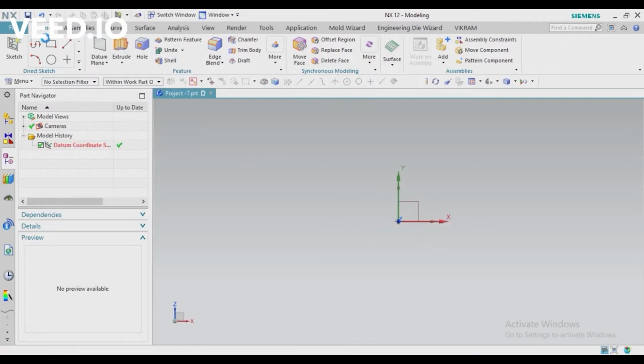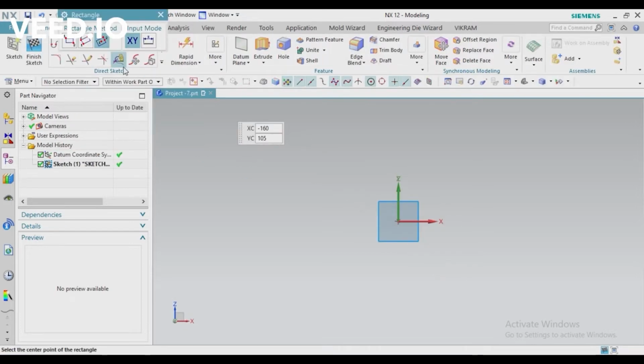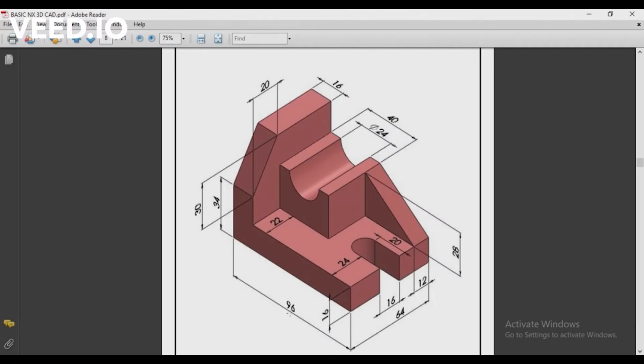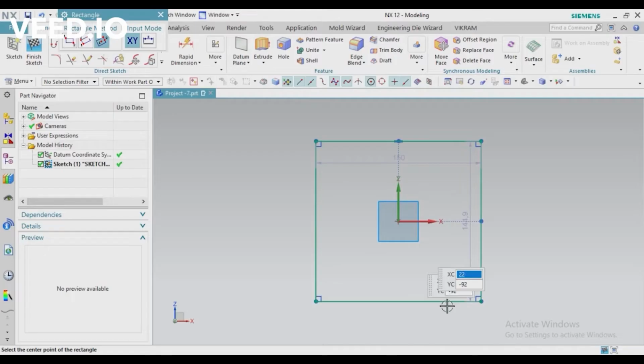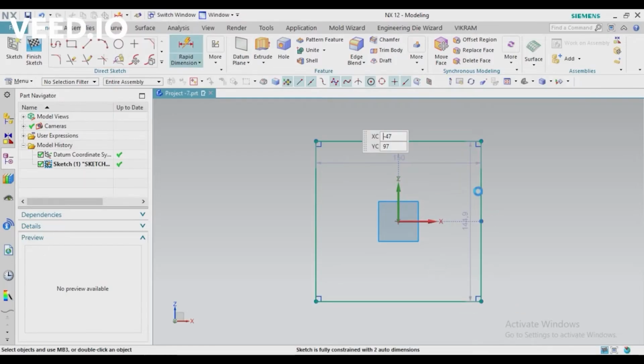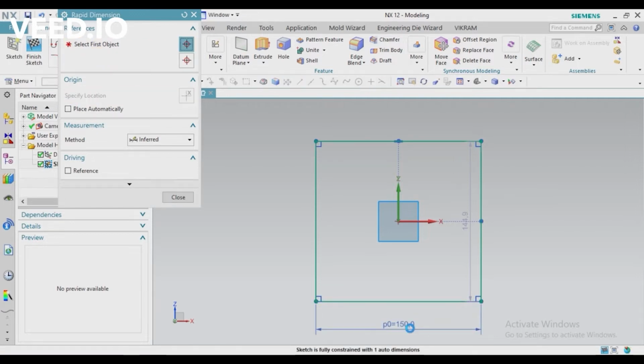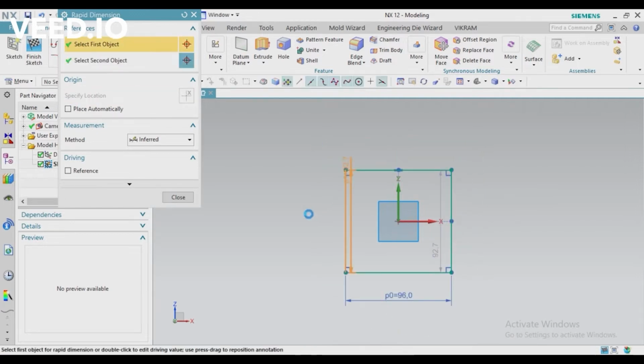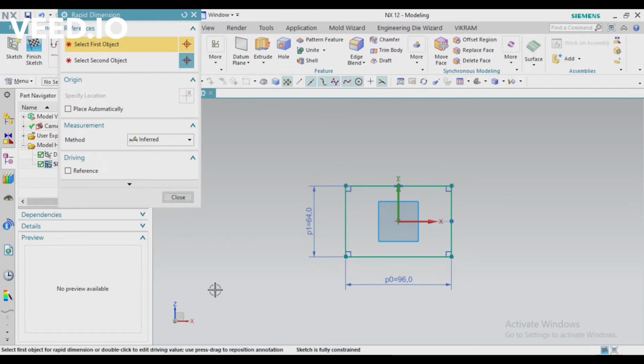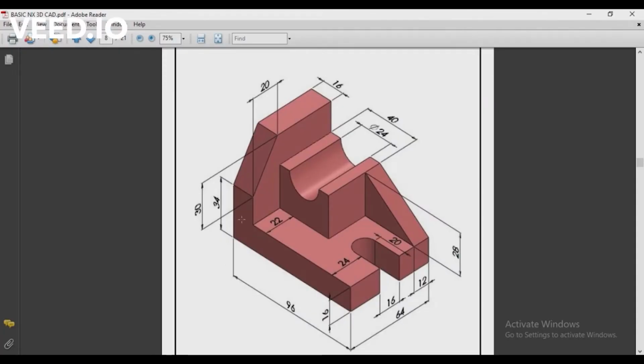Click OK. And just first create a center rectangle. Okay, so length is 96 and width, you can calculate, 64. So define those values. Length is 96 mm, and width as I calculated is 64. Then next, the inside line I have to create with an offset value. How much? 16 mm. Okay, so both sides you can see.